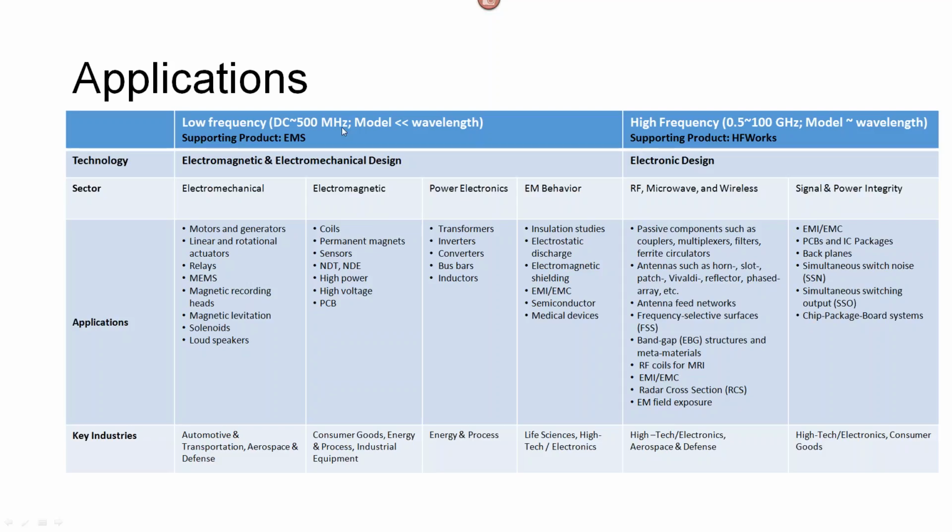If you get into a few hundred megahertz, that's really where we may have to resort to the other package that you see on the right side. But as far as kilohertz are concerned, we will have no problem. And EMS does take into effect the skin effects produced due to high frequency, so all of it is automatically considered in the product.